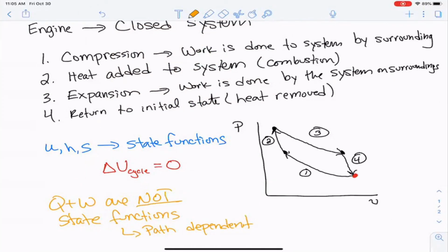And let's assume for just a second, I actually can show you this visually, that steps 1 and 3 were isochoric, that steps 2 and 4 were isochoric, and we're going to do this for Carnot in a minute anyway, and steps 1 and 3 were isothermal. Well, if that were the case, then you would only have work done in steps 1 and 3. And just look at the area under the curve, right? Because it'd be the integral of P dV at constant T, right? So that would be the work that you had to do. And then this one here would be the work that you got out of this cycle, right? And thank goodness that the work that you get out is greater than the work that you put in. That's the whole point of what we're trying to do.